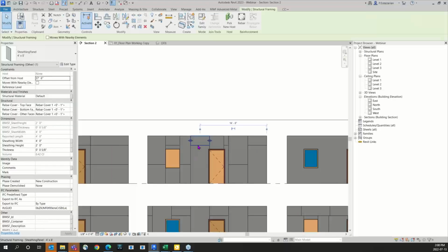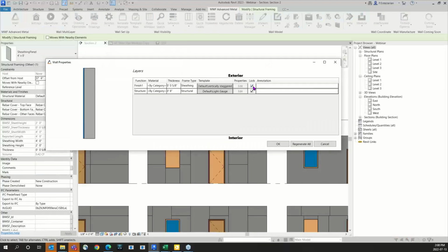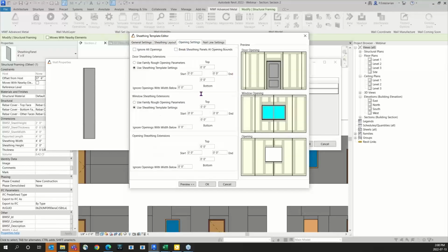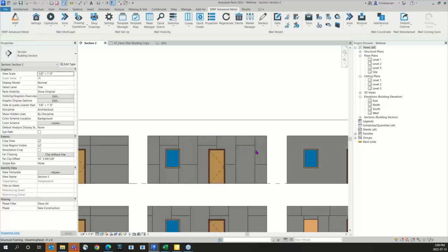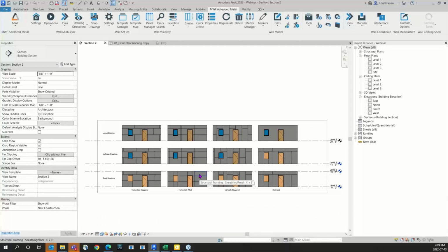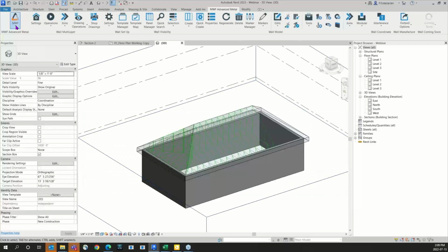And the last option that we are going to try here for our multi-layer panels is at center bay. So unlock, edit. Let's switch it to at center bay and uncheck break sheeting. Okay, and regenerate all. It will place the full sheeting at center bay and it will continue placing the sheeting to the edges. So these were the new features that we have added for our multi-layer panels and specifically for sheetings. Now let's switch to our Truss module.